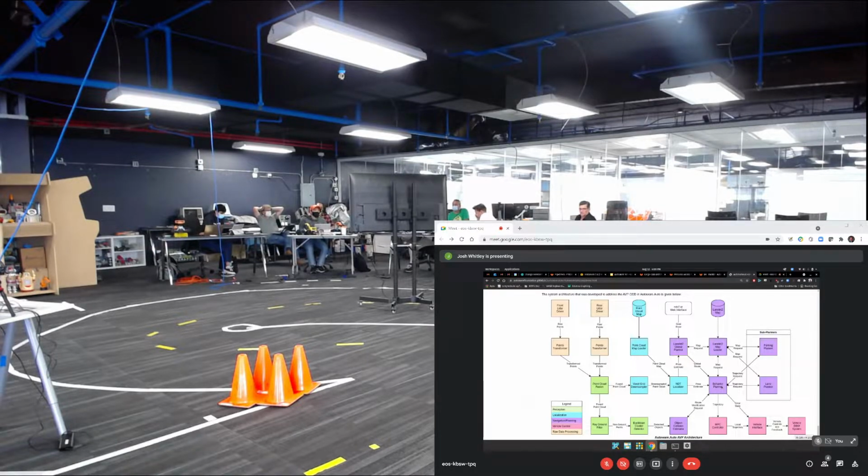So if it's a lane, for example, we would use the lane planner, which basically just creates a virtual center line on the lane and then sets a bunch of waypoints down. If, for example, we were trying to get off of a lane into a parking space, then we would call the parking planner. It sets up a bounding box, which is the lane plus the parking space that you're trying to get into, and a set of virtual boundaries. And then it solves the problem of how do you create a path that moves into this space without hitting anything.